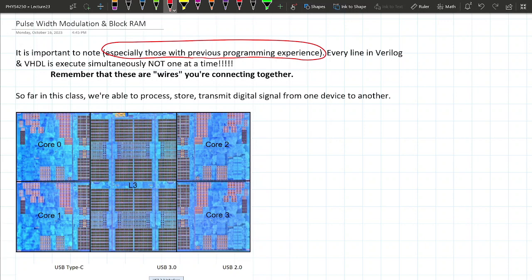In hardware description languages, that's what HDL stands for, think about it as programming which wires get connected to which wire. Once those connections are made, those wires are permanently there. So whatever C equals D is, it's going to be C equals D all the time, no matter what, because they're physically connected. If C is high, or 5 volts, D is always going to be 5 volts. Even if you try to change it later, it's not going to allow you to do that.